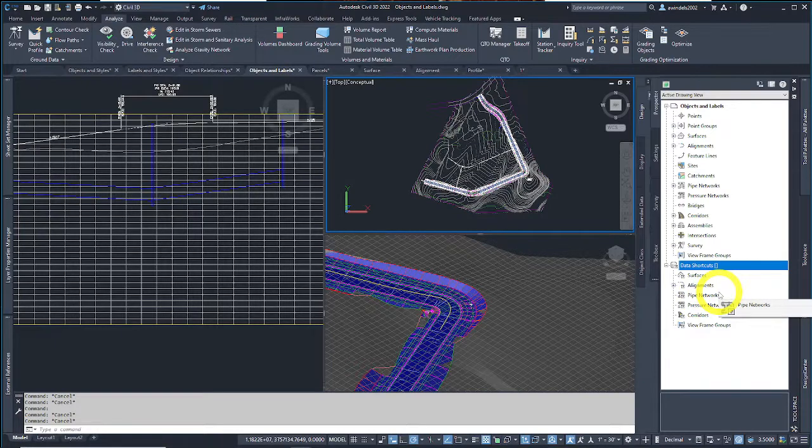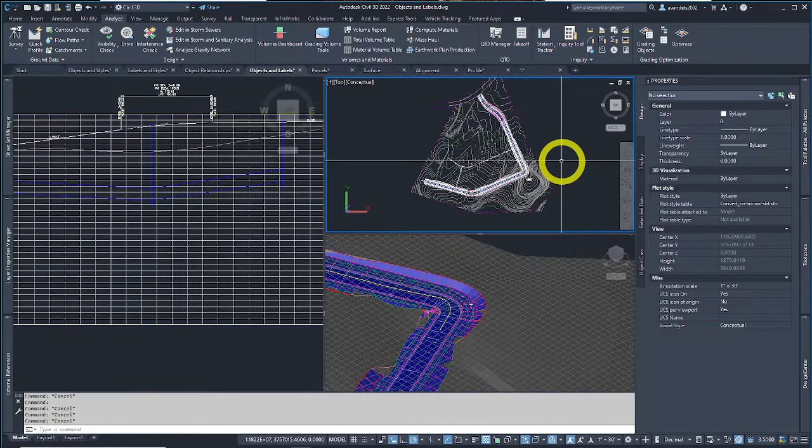So we're basically using a data shortcut to connect objects to objects, so different drawings amongst each other. A data shortcut is basically a link to a Civil 3D object that enables another drawing to get access to that object through another drawing. It says, where's the source drawing? Let's bring it to this destination drawing and let me manipulate it to a certain degree in this destination drawing while keeping the source drawing relatively pure in a way. So it's not totally edited, but it can be edited how it looks in the destination drawing, if that makes any sense.